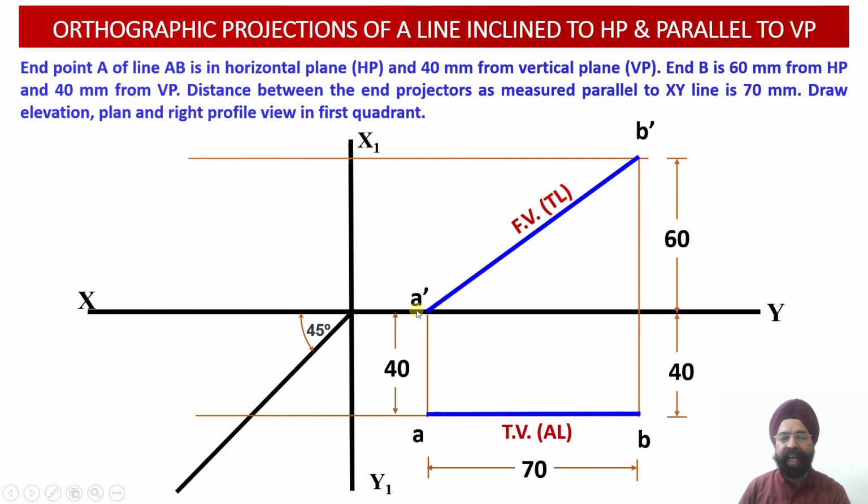So we assume that we have drawn a horizontal construction line through A dash, on which we are going to mark the distance of the point A from the plan into the profile plane, and we will obtain the location of the point A double dash on the same horizontal construction line drawn through the point A dash.